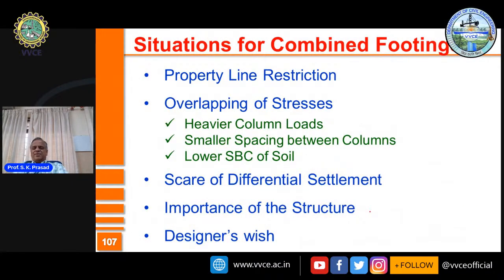Well, friends, I just want you to understand that it's always better to go for simple foundation. That means, given a choice, we'll go for isolated footing. For every column, one single foundation. But not always you'll be successful. You may have to yield, you may have to change. Let us see when we change to combined footing.